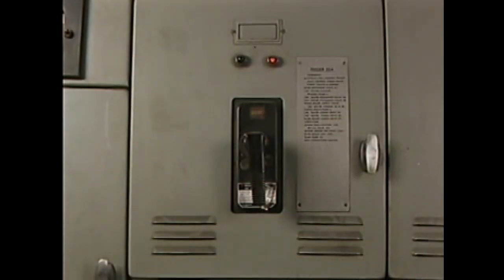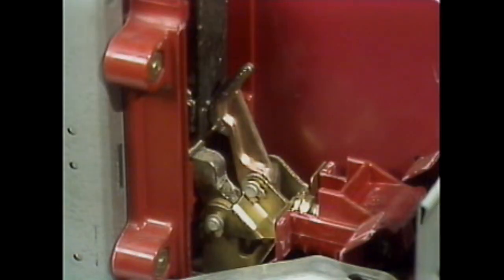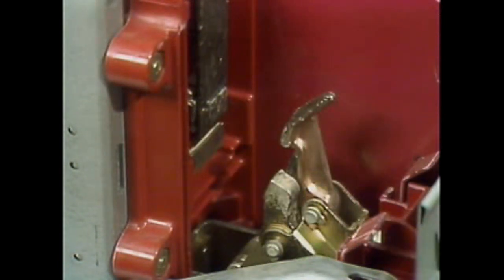One type of component that's found throughout a plant's electrical distribution system is a circuit breaker. Circuit breakers serve as protective devices, and they also provide a way to isolate electrical equipment from a source of power. When it functions as a protective device, a circuit breaker helps prevent excessive current from damaging circuits and equipment. A circuit breaker is able to do this because it has electrical contacts that open or trip to interrupt current flow to a circuit. When it functions as an isolating device, a circuit breaker is tripped by personnel to isolate equipment from a source of electric power.